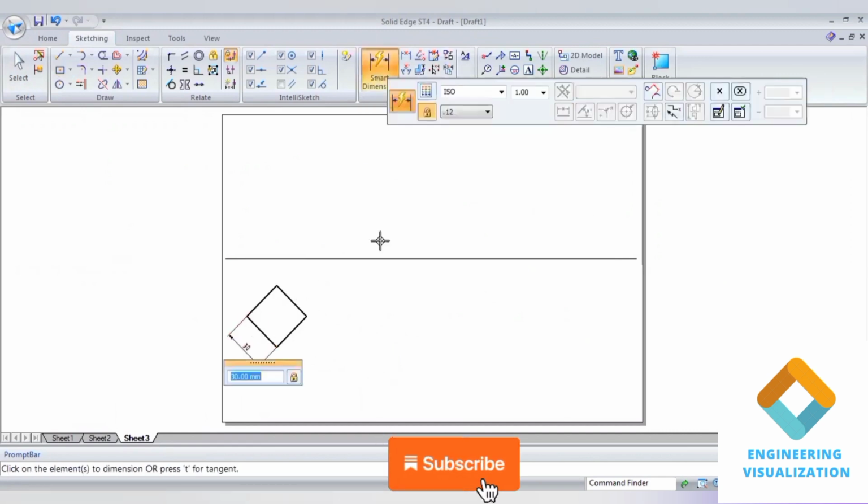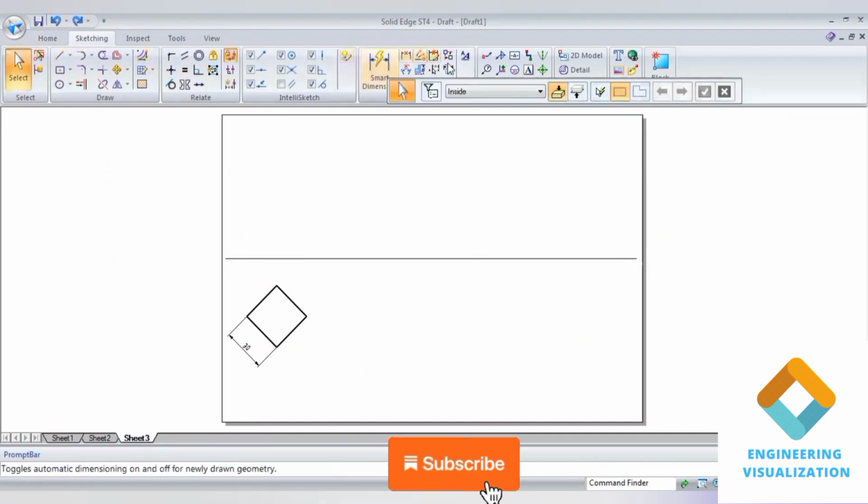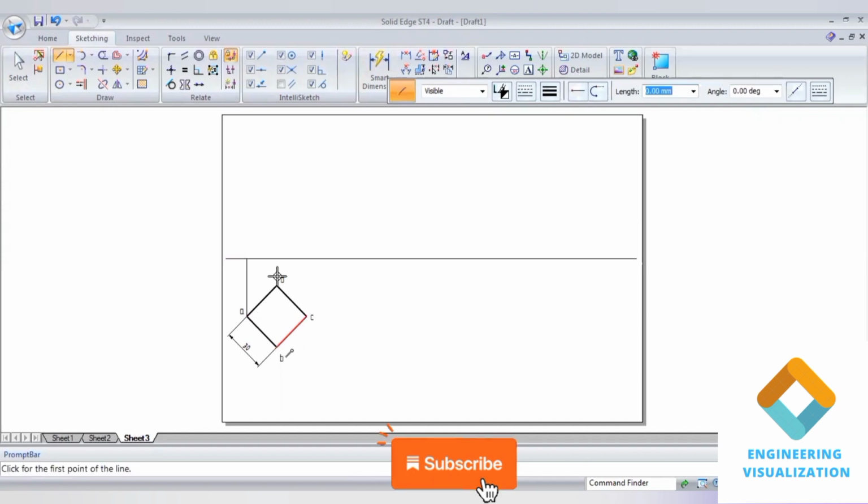You can show the dimension for one side, and write the namings in small case letters. So drawing the projection line here. The front view axis length is 60 mm.